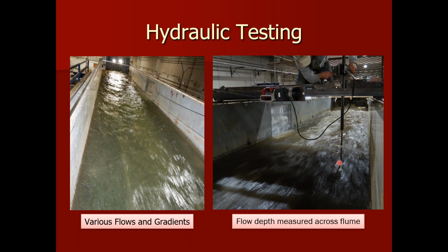So it was important for the guys to go through with a point gauge and very carefully, accurately get the water surface throughout this test reach. Three locations across the channel and every 2 feet down the length, so that we could rebuild that hydraulic model and determine what the stresses were.